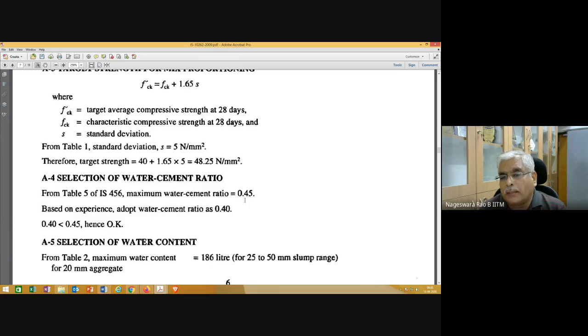Here 0.45 is what the code is specifying, but based on experience, water cement ratio is assumed as 0.4. That is fine. And if you say, I don't have experience, what should I do? Then you go ahead and use 0.45. Anyway, once we do all the calculations, we need to do trial mixes, and then finally arrive at the actual water cement ratio.